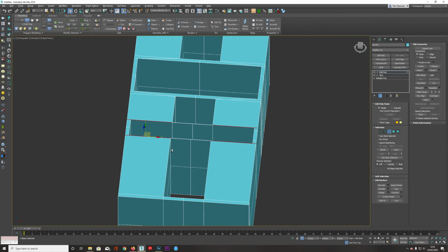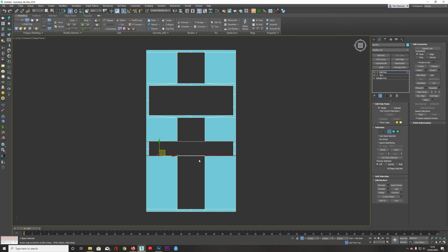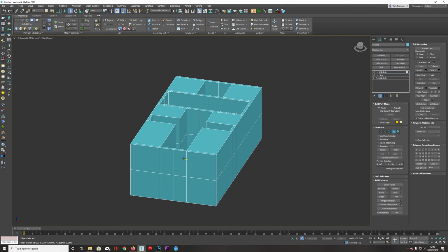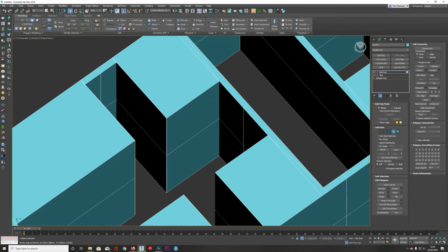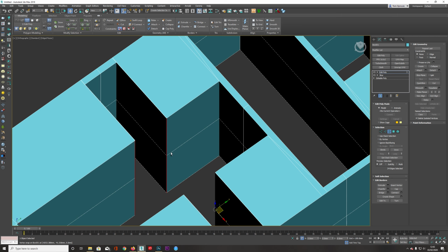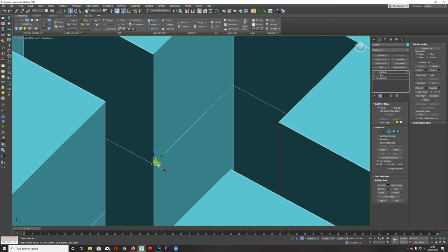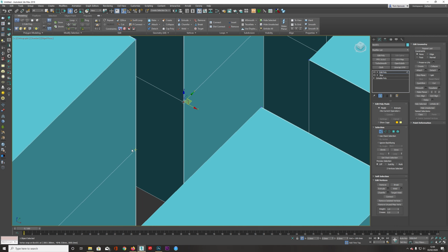Alright. And now by doing this I can do what I wanted to do in the first place. I can just go into 4, polygon mode, and I'm actually just going to delete these out. I wasn't sure what I was going to do with those, but I think for now I'm just going to delete them. Press 3, press Control A again. I've got these selected, just do cap on those. And then I'm just going to come in. I just want to make this clean, so I'm just going to take these two and connect these. And I'm going to do that with all of them.